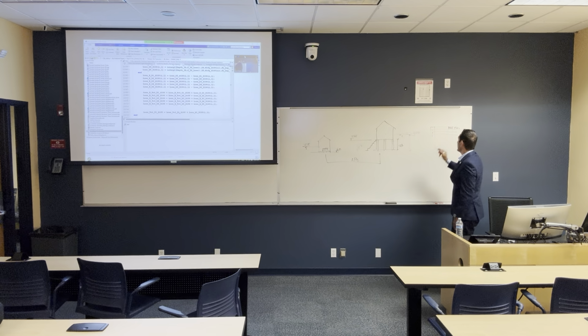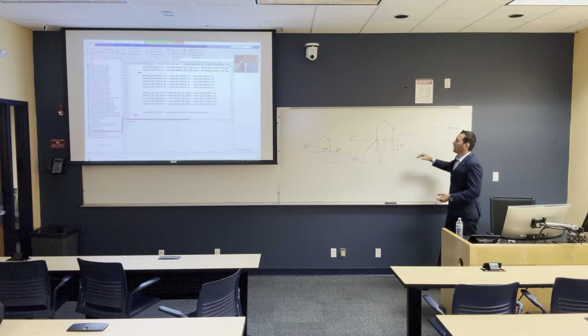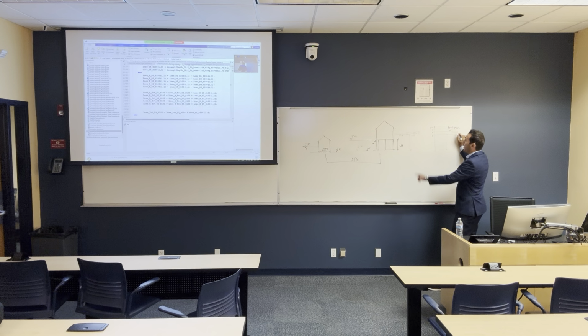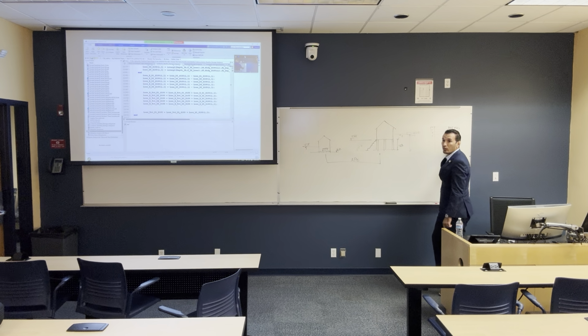You increase the elevation. So let's say this one was like 124, then you plus 12 feet. By the way, this is an elevation, not height. But let's say not 124, because most of the buildings on the shoreline have an elevation of 0. So let's say the first floor elevation is 5. Okay? Then you add 12, it's going to be 17.